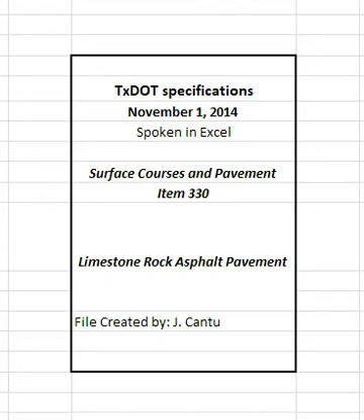4.4.1 Weather conditions. Place the mixture when the roadway surface temperature is 60 degrees Fahrenheit or higher unless otherwise approved. Place the mixture only when the weather conditions and moisture conditions of the roadway surface are suitable in the opinion of the engineer.